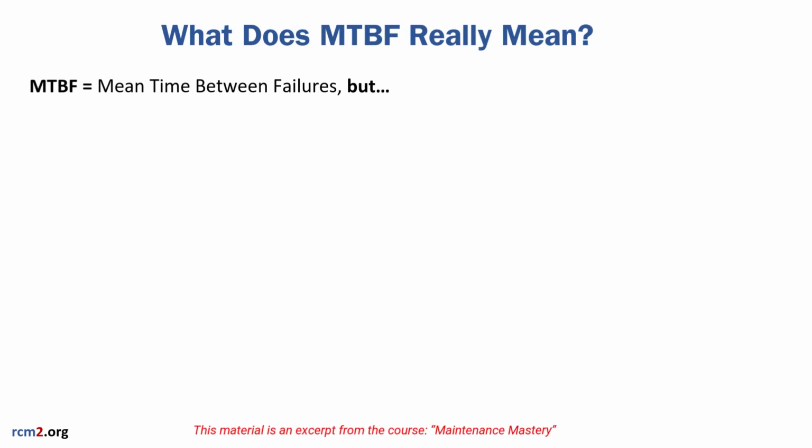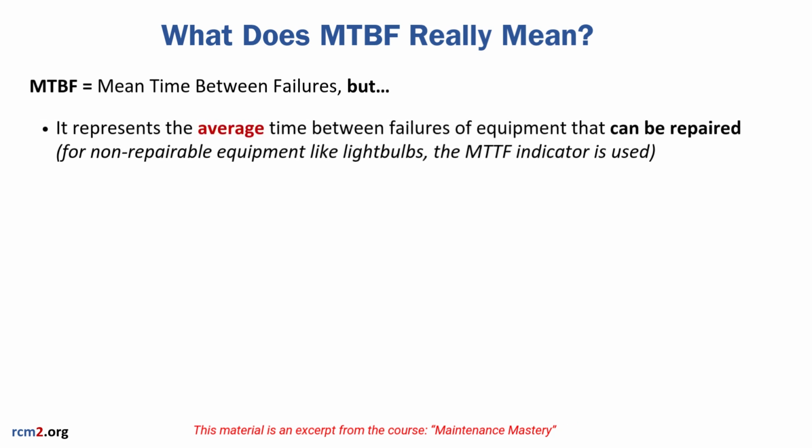MTBF, or mean time between failures, is one of the most frequently used, but also one of the most commonly misunderstood reliability indicators. In practice, it represents the average time a device operates between failures, provided that the failure can be repaired. For non-repairable equipment, like a light bulb, we use a different measure called MTTF, mean time to failure.